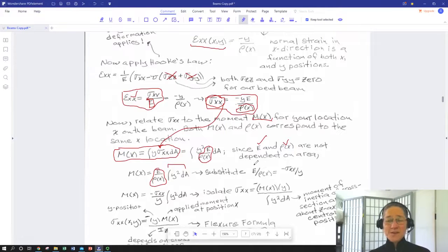let's resubstitute, because we've still got, tensile modulus is easy to look up, but we've still got this expression for rho at the bottom. So we're going to do a bit of a double substitute. So we get rid of this expression for rho, which is, again, something you'd have to measure. So we're going to go back to this formula and say, if we divided both sides by negative y, we could say sigma xx divided by negative y is equal to tensile modulus over rho.